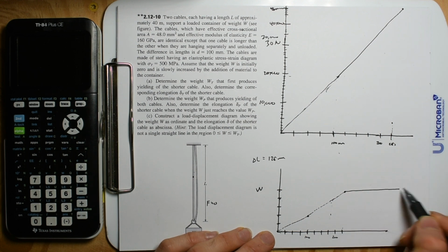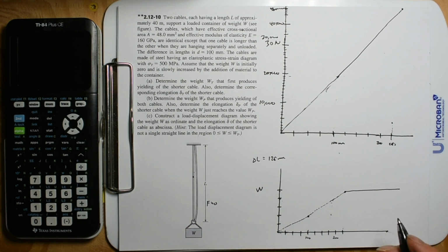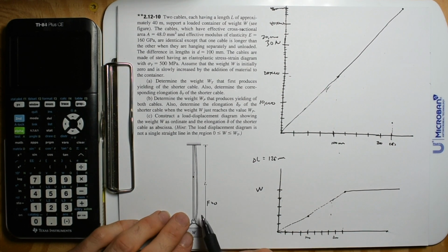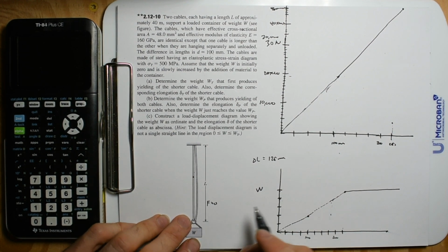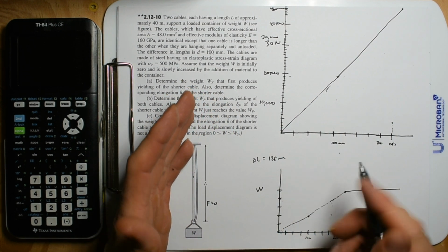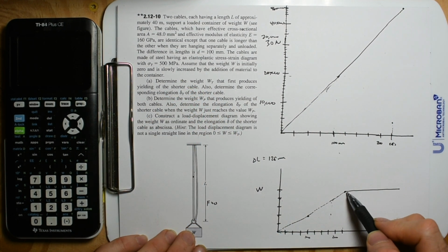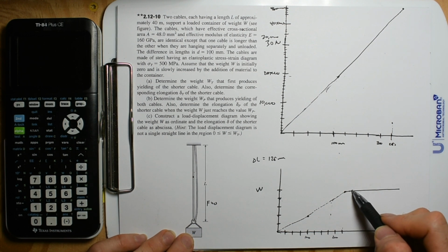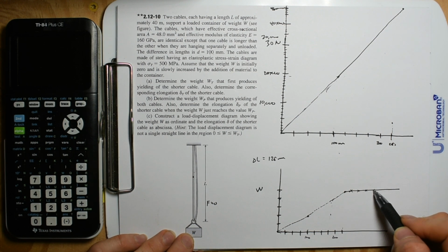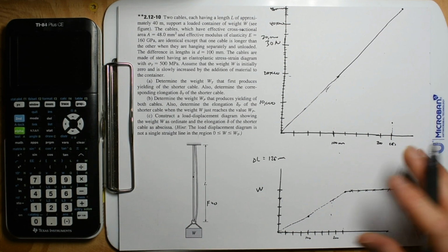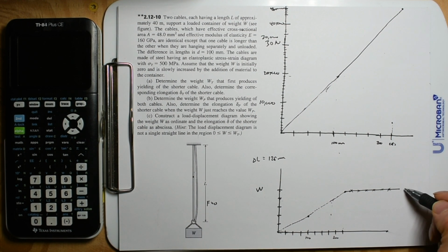Oh yeah, it's just that way. And it's significant, you know what I mean? I want to go to the hardware store and start reefing on bolts, because the second they stretch out past their elasticity, they don't go back to the normal shape. But once you do that, you know that you're putting a constant force into that bolt. So it's just fascinating. And if you know the material properties of that bolt, you can kind of tell the force that you're putting into it.